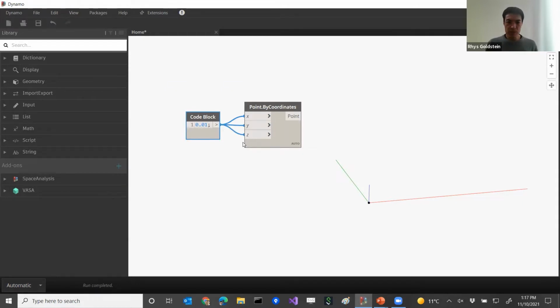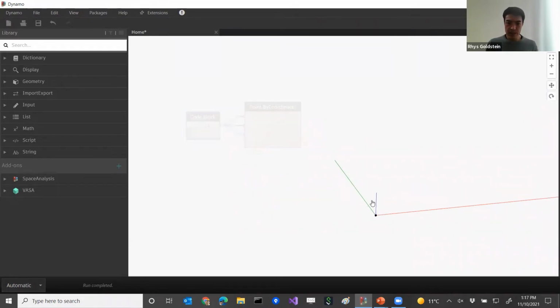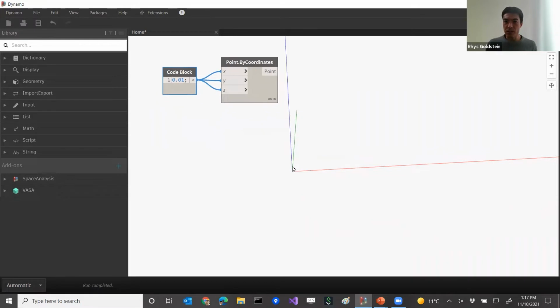The reason we're doing that is just to move the point slightly off the origin, because if we zoom in and the point is right at the origin, it's actually on the boundary between several voxels. So here we've offset it slightly from the origin to make sure it's entirely within one voxel.